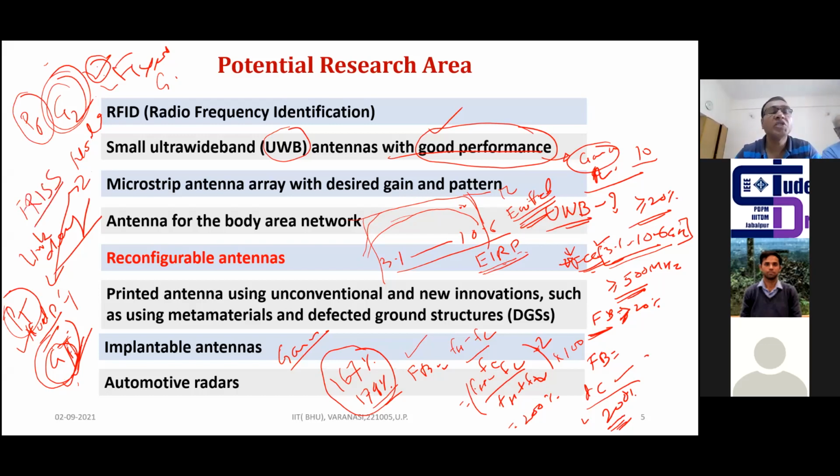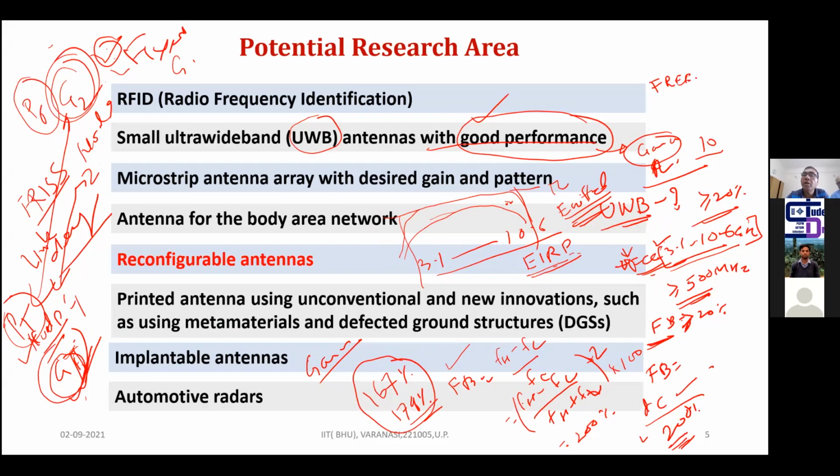So you just go through the Friis formula and design the link budget, considering the entire losses in the link. The entire losses include, one, the free space path loss. The rest depends on which environment you are in: the urban environment, rural environment, room environment, or what kind of scattering environment we have. Based on that, you have to consider the environment.